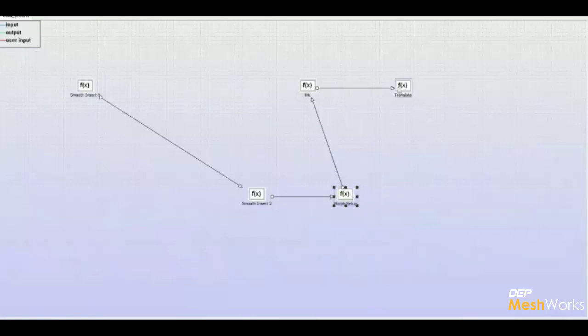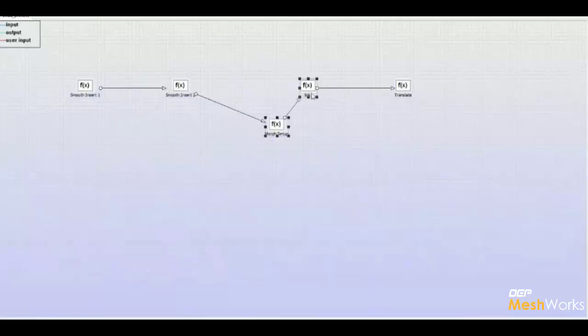So next, after the offset creation, we will be linking and unlinking it. Even if in this particular process we delete something, let's say this link, I'm deleting it, we need not worry, because in the functions panel here on the left side we have all the tools, properties, basic mesh, all those panels. Whatever pre-processing panel we have, we will have here also.